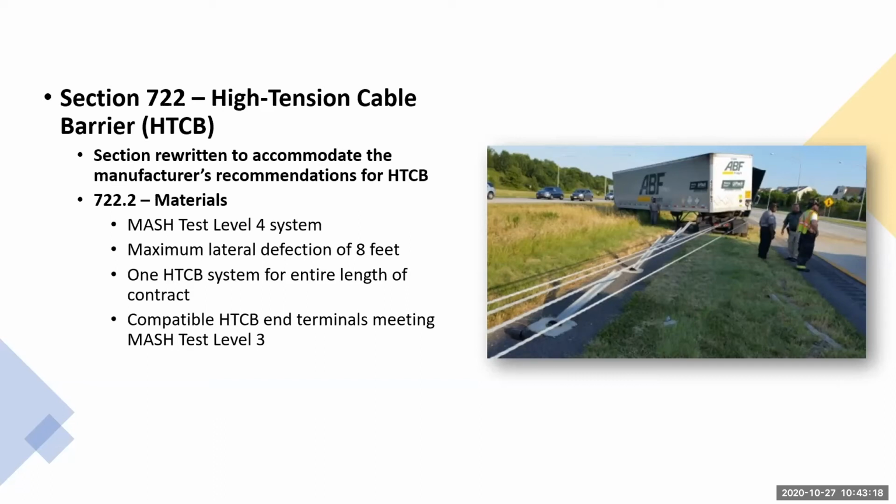If you're doing multiple runs of high tension on one contract, it's one system on the entire contract. We're not going to interchange systems on one contract. And then the high tension also requires a compatible end terminal, and that end terminal meets MASH test level 3.